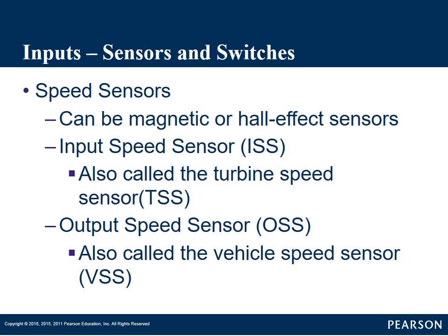They monitor that gear ratio because in first gear they're expecting a certain gear ratio. If the input speed sensor is turning at a much different rate than our output speed sensor than what it's supposed to, it's going to show a gear ratio that is off, and it'll set a code. That's a good sign that the transmission is slipping. The clutch packs are slipping in the transmission.